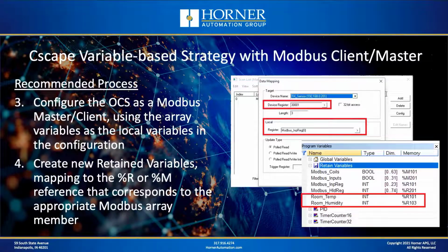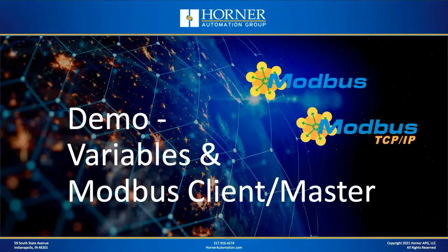And then the final step is effectively to go back to your variable editor, add in whatever variables you're going to use in your program that you want to ultimately have tied to that Modbus data, and then map it into the appropriate register location. And we'll again cover that with a live demo here in a minute. Let's go ahead and move to that demo now.